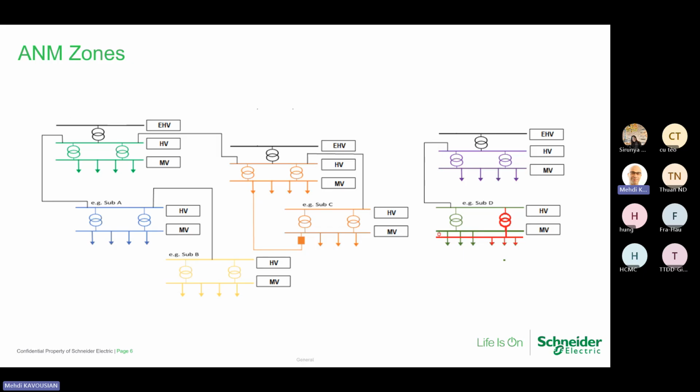Sometimes you have two substations and you tie between them. These will be done together, because from a topology point of view, we are connected and it runs together. And in a case where you have one transformer between them and this bus tie switch is open, they are not electrically connected, so you can say this is one zone and this is one zone.